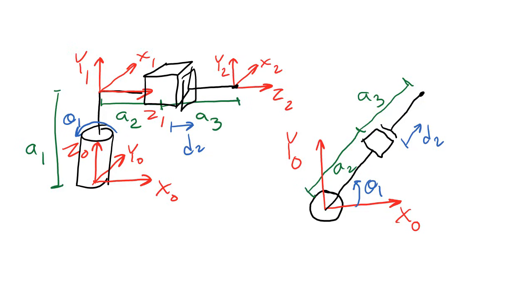Now, the graphical approach to inverse kinematics relies upon us finding triangles that we can use to write relationships between the joint variables and the xy position of the end effector. It takes a little bit of trigonometry experience and just some experience solving these problems to help you see which triangles are going to be useful. One of the triangles that is basically always useful is this triangle that I'm drawing in purple right here.